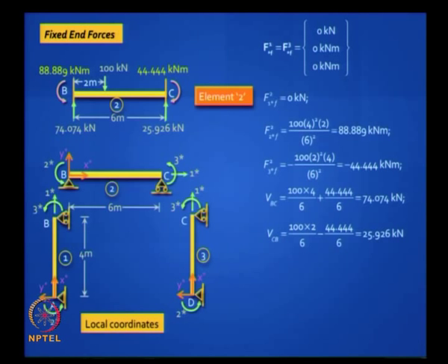We have done this calculation in the conventional stiffness method, so I will not repeat it, but it is important to work out those vertical reactions. In the conventional stiffness method, those vertical reactions went into your fixed end force vector because you had some coordinates there, you had 6 degrees of freedom. Here you have only 3 degrees of freedom, but you still need to work out the vertical reactions. Why? Why do you need the vertical reactions?